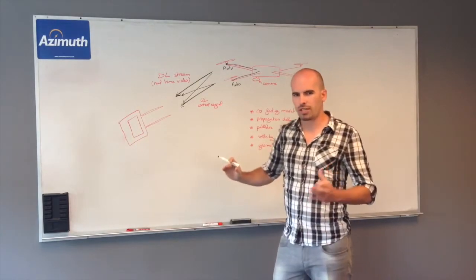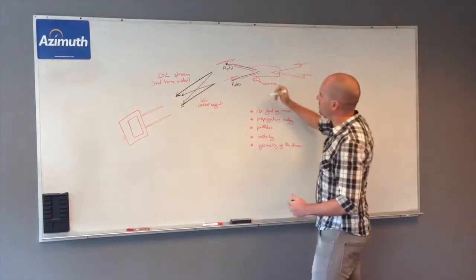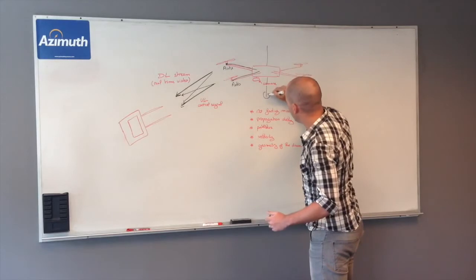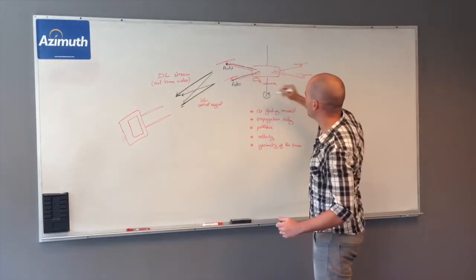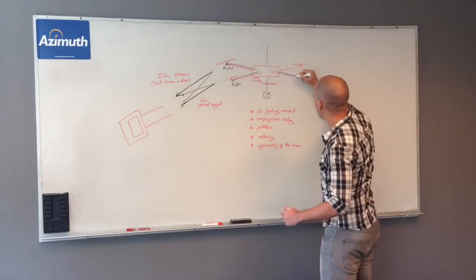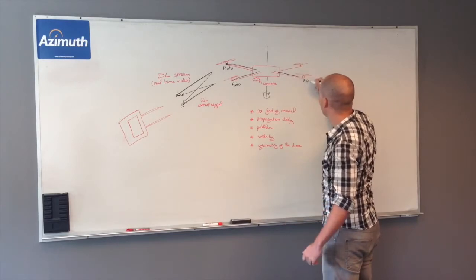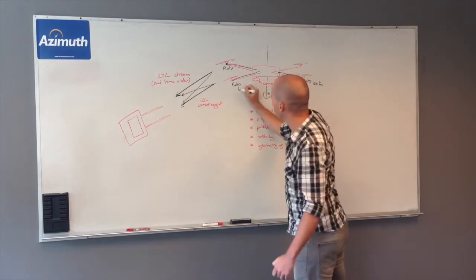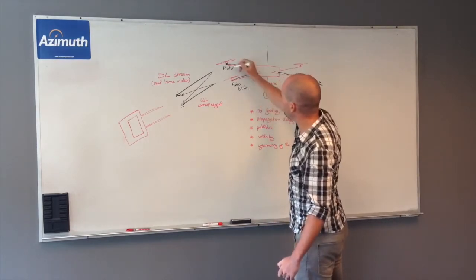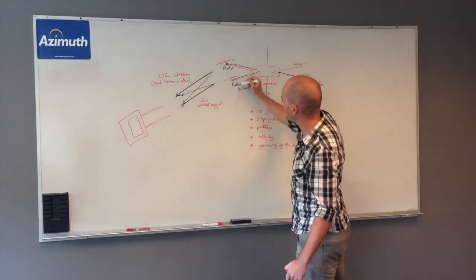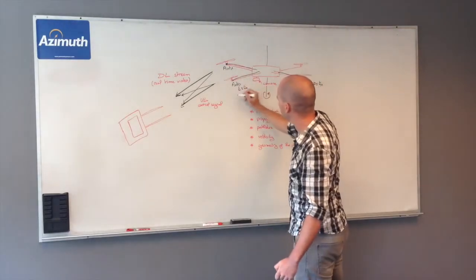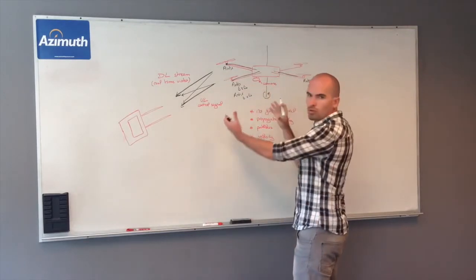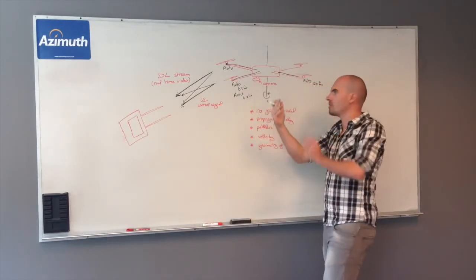But there is some corner case that we have to study. Imagine that your drone is rotating on itself. At some point, antenna 0 will be here now. So this would be antenna 0 at time t1. This one, antenna 0 at time t0. And this one, antenna 1, will get to the antenna 0 location actually. So this will become antenna 1 at time t1. So the drone just rotated on itself.